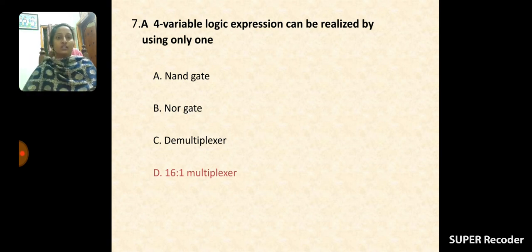From decoder also: if it is a 2 by 4 decoder, when is the output Q3 activated, and what is the main difference between the decoder with enable input and without enable input? If enable input is equal to 0, how is the output produced, and if enable is equal to 1, how is the output produced? In this way, in your competitive examinations you also face such questions.